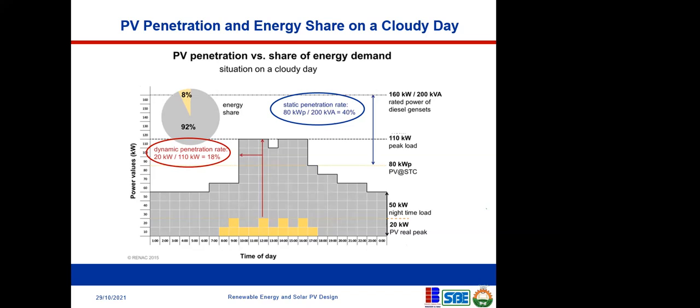Your solar systems are rated in kilowatts, and that's why we're using the installed capacity in kilowatts. But if you're talking about the dynamic, then the load becomes important here, right? So if it's a pure resistive load, then in that case your kilowatt becomes equal to your kVA.